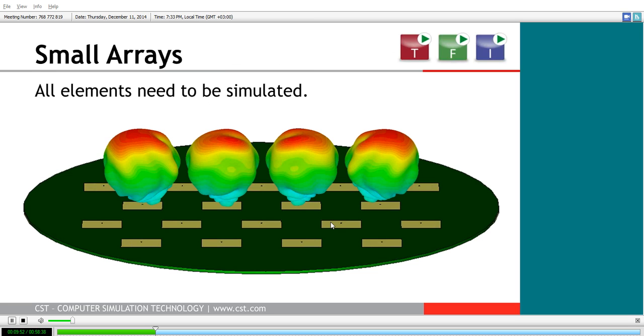There are two different approaches in terms of how we can achieve the excitation of this array. The most obvious, of course, is to individually excite each port and obtain a full S matrix. This is obviously quite flexible because then we can experiment with different beam weightings in a post-processing capacity. The downside to this approach, at least from the perspective of a transient analysis, is that this would necessitate that each of the ports are excited and simulated in series, which gives you an n times linear increase to the overall simulation time.